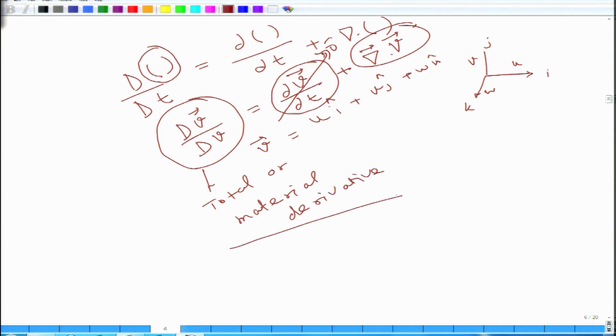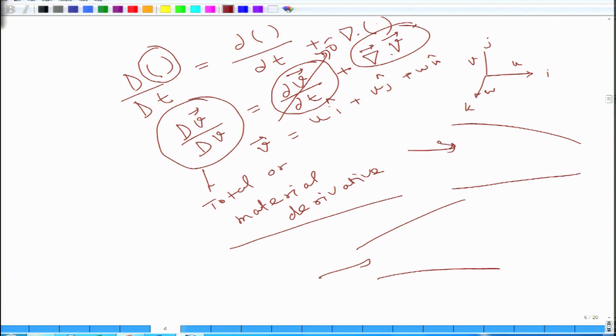is still not 0, because this term is still allowing you to increase or decrease the area along the flow. That means the flow can still be a spatially dominated phenomenon, and hence it can accelerate and decelerate. Therefore, in the steady case, it does not mean that you are not allowing the flow to be accelerated or decelerated. The time dependent change of the property you are ignoring.